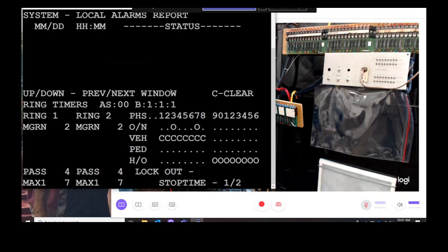There's nothing in there. So now it's telling me that it didn't register a problem. So now I'm thinking the controller's not registering the problem. This most likely could be a field problem. It's not a cabinet related problem. Again, we're always trying to identify: is the problem in the field or is the problem in the cabinet?